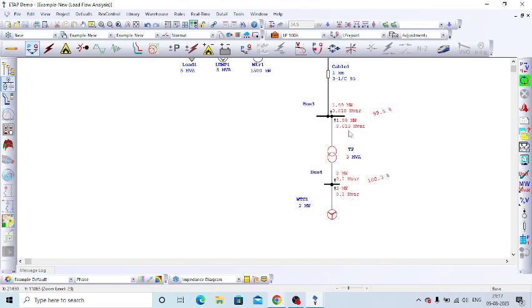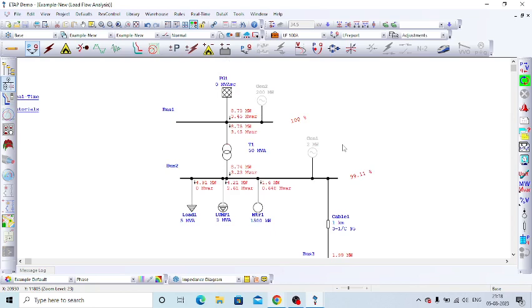You can see on this transformer high voltage side, it is not 0.1, it is 0.018. The sign is positive. Last time it was negative, now it is positive. It means both real power and reactive power are flowing from this generator towards the system. Earlier, reactive power was consumed from the system by this transformer. Now the transformer is consuming reactive power from the generator, so only the remaining reactive power is flowing into the system.